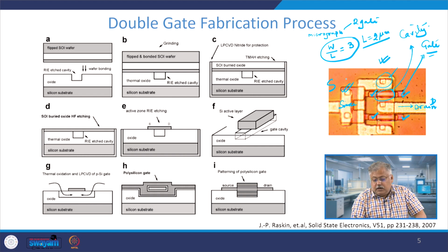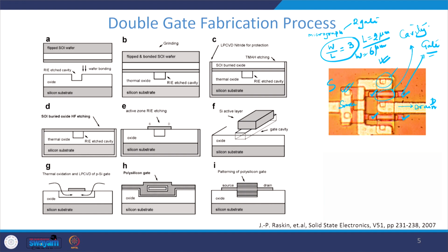So, effectively the width is equal to 6 micron. In a sense, in an example of using a single structure with two fingers, I will be able to generate 2 DG-MOSFETs at this particular point, and the gate is available here.